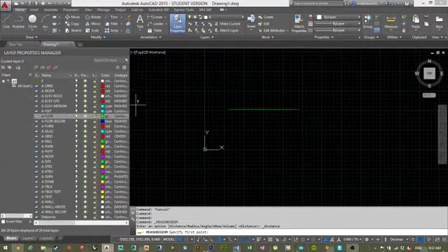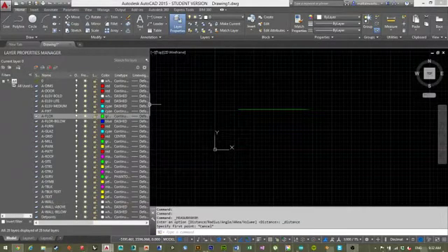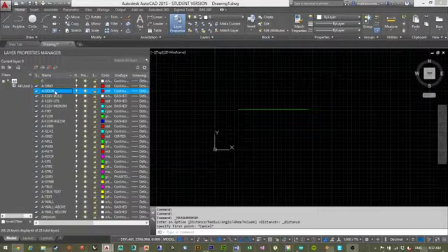All right. So part of that template that you got was this whole list of layers, and I'll go kind of through them. So again, I've divided all your drawing line types. Going through a project, I'll probably add some. So I have wall above and wall below. Those are similar, but you can see that I've turned them to dash lines, just indicating on my drawing that there's a wall above or a wall below.